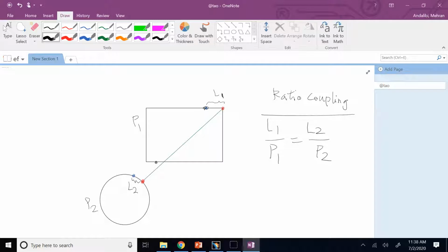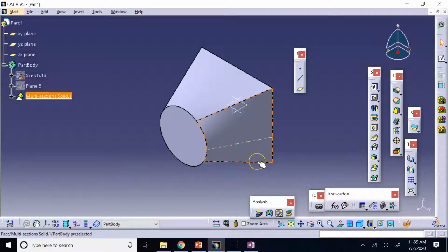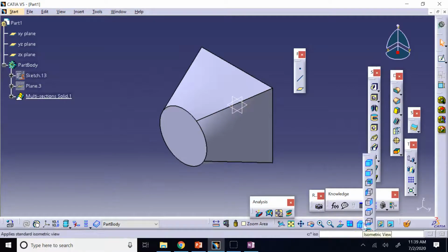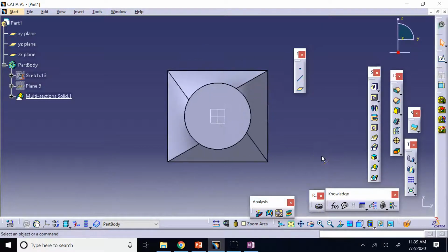That's the twisting. If the initial points that it chooses are not well in front of each other and not well matched, then when it goes to the next point and connects, and then goes to the next point and connects, and so on, you see what? You see the twist, and that's what is happening over here. The reason for the twist is because the closing points are not exactly in front of each other, because the closing points are not well selected by you or by the software.